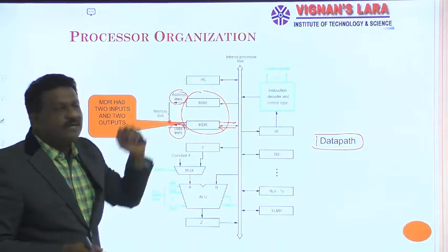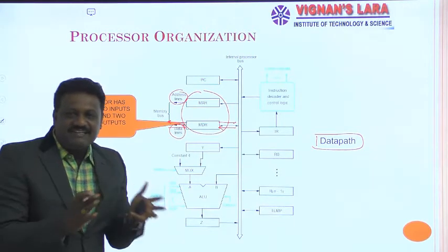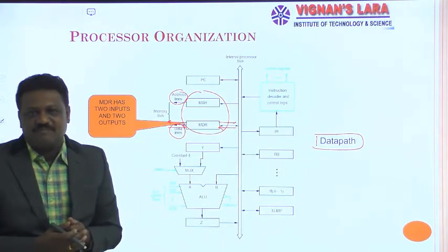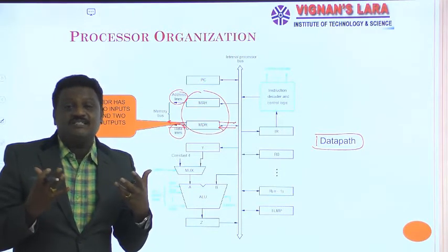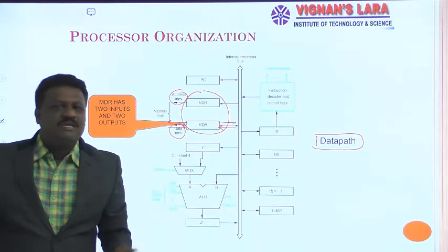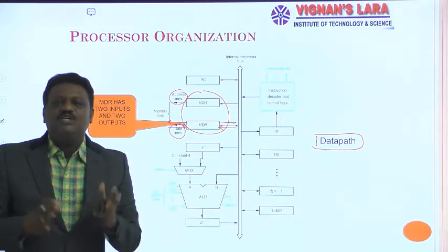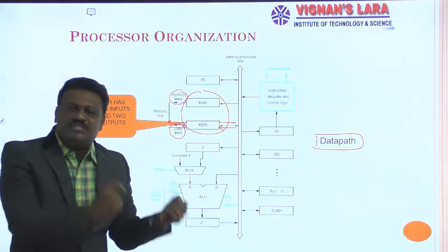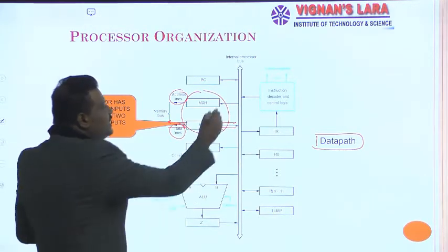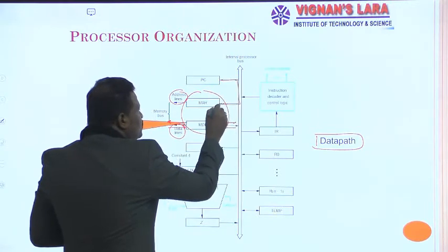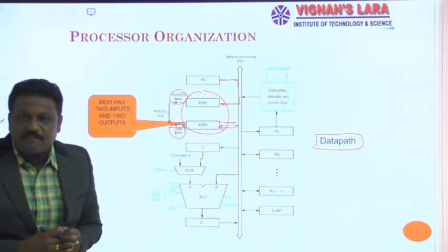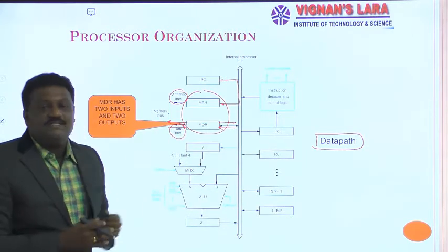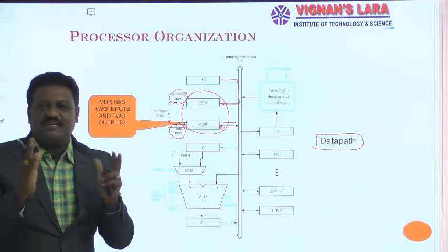So this is my program counter PC. One interesting thing is that generally your PC provides the address of the next instruction, but the PC generated address can't be directly transferred to the memory with the help of the address bus. Here what happens is that the address your PC generates to fetch the next instruction from the memory is transferred to the register MAR. Later MAR transfers that address to the memory with the help of these address lines. So that is an important thing.